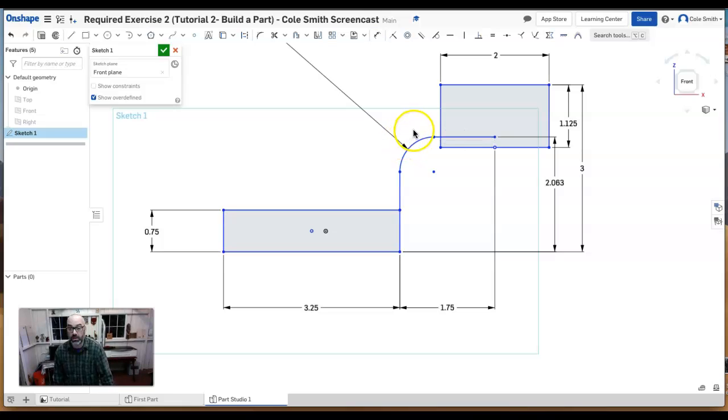Oops, I'm still on my dimension tool. I'm going to select this line, this arc, this line, and then I'm going to go up to my offset command, and this thing pops up. There's kind of an arrow going on either side of it. I want to bring that arrow over to the side I want and pull it up, and then when I click, I get my text box, and I can make that a 0.75 offset. All right, man. Hey, this is looking pretty darn good.